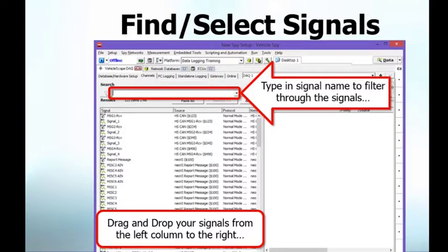However, on the CAN messages, you're done. On doing things like diagnostics and memory reads, there's a little bit of extra setup. So one of that is going to be, we default to what we call normal periodic rate. If it's like a direct memory read, you right-click on the message and you can change the speed. So we have basically a fast, normal, slow.